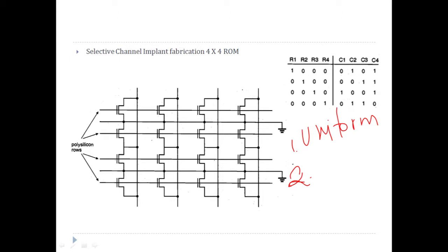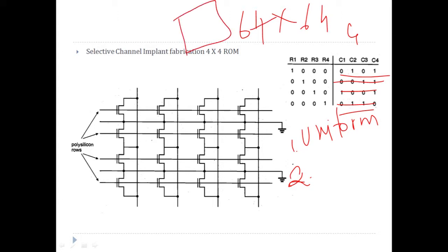So it can have several bits like this. Suppose this is the output and it is just 4-bit, but it can be 64-bit or of any size. In that case, I will just have a simple layout structure, let's say 64 by 64-bit size. And this will be a standard NOR ROM I will have.